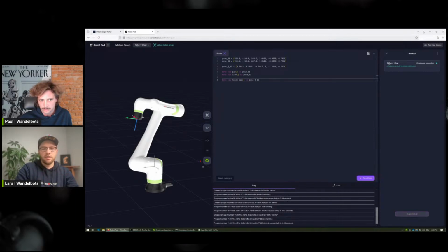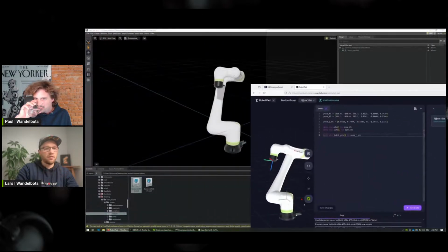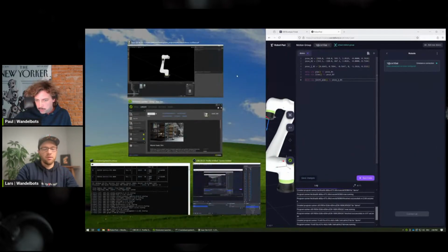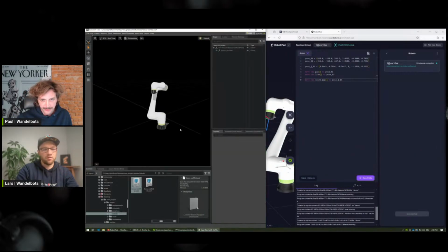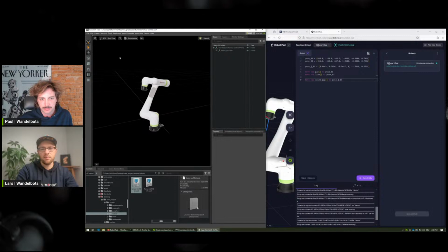And if it's connected, we can then see in Isaac Sim that it took over the pose of the NOVA robot. And now we can also use the commands for jogging, programming, and so on for the Isaac Sim counterpart as well. Let me make it a bit bigger.